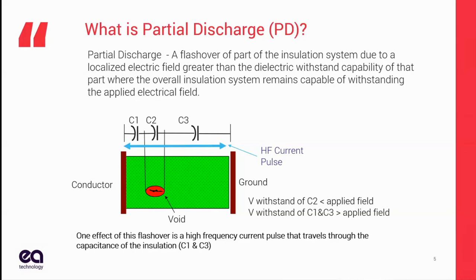So partial discharge is this current flow as a result of the insulation section not being able to withstand the voltage applied to it. So we get a current pulse that's equalizing the voltage on the capacitance. It is unipolar. It is very fast because we're talking about small capacitances. It's typically a couple of microseconds, and it's unipolar, and then it's going to go from one direction or the other depending on the polarity of the sine wave.